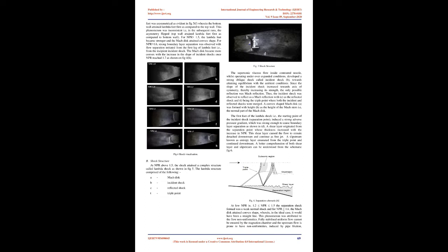Intensity of light falling on the camera was controlled using a knife edge placed at the focal length of the second mirror. Shock waves being regions of high density, beams of parallel light rays bend as they pass through regions of density variation, due to the change in refractive index. The refracted light rays thus deviate from the parallel path and do not get blocked by the knife edge, forming a bright image of the shock wave on the camera. The experimental arrangement is shown in Fig. 3. Fig. 3: Experimental setup.